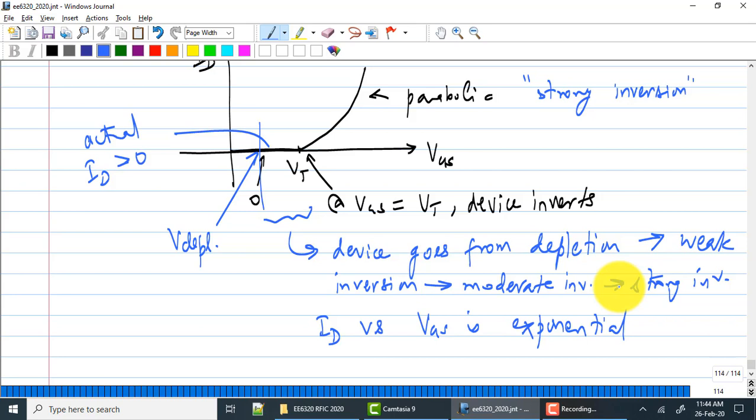Okay, so now what you're saying, VGS minus VT less than 200, there is no case where you can put out a magic number saying 200 millivolts. What I can tell you is that in most modern devices, the range of voltages that the device spends in moderate inversion and weak inversion has become larger and larger, right?